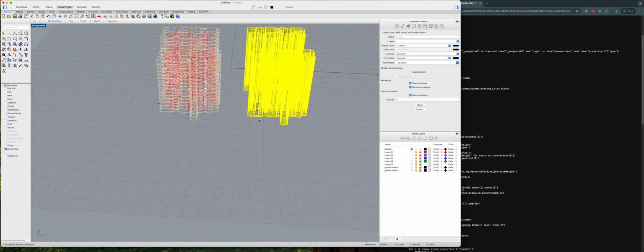All right, and then you can do things like SelColor, I believe, which allows you to select everything the same. Grab that. Yeah, enter. And now I can ExtrudeCrv, and I can extrude at 1.2. There we go. So I grab those curves and I turn them into geometry, and you can see now how slow this is on the computer. But you're free now. You're free to work. Should be a bit faster in render mode.